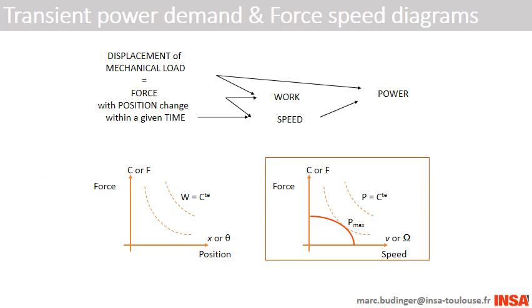Mechanical loads to displace by the device we conceive can be characterized by certain notions, such as displacement, rest time, speed, power, and energy. Operational limits in the transient domain can be represented by a power plane like the effort-speed one. These effort-speed characteristics, or effort-position, allow us to represent, in a graphic way, the principal mechanical attributes of an actuator: effort, speed, and, as a product of those, power.